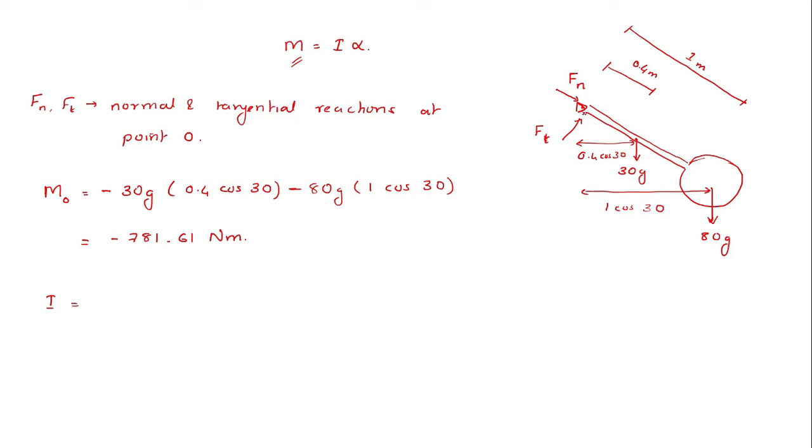This can be done by using the parallel axis theorem. Okay, so remember one thing in mind, I am finding the moment of inertia with respect to an axis that is perpendicular to this plane of this screen here. Okay, so as such, I will be equal to, now first I shall look into the sphere. Now for a sphere, you know that we have studied that the mass moment of inertia with respect to an axis that is passing through the center of the sphere is given as 2 by 5 into m r square. Okay, 2 by 5 into m r square. Let me call it as, now plus m into the distance, okay, the distance between this corresponding center of the sphere and this point, I'll call it square.